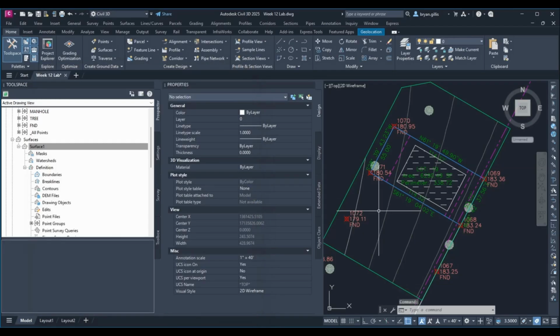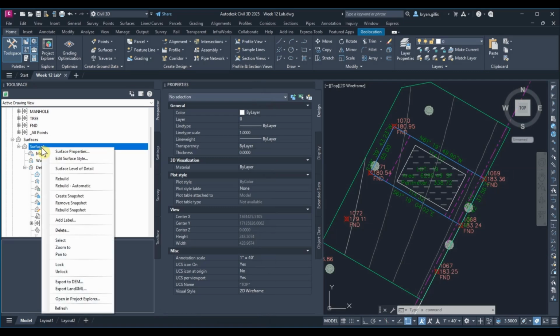That's going to give our client the ability to understand, hey, are there any major changes? No, I could see right here, it's a steady slope. It's not a lot that's gone on. It's nothing I need to worry about. We'd also have something, especially in an area in Nueces County, we'd have an elevation certificate because they're going to need to know their floodplain rating.